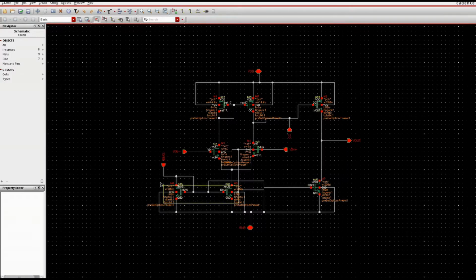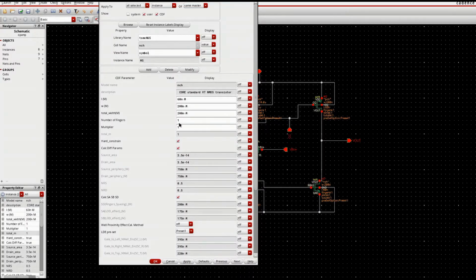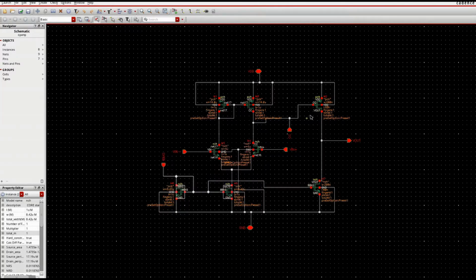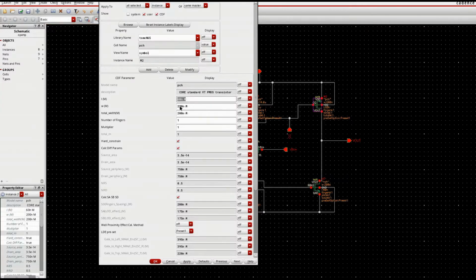Next, these two MOSFETs are equal as per the design. W is 8.42 micro and L is 1 micro. And this is, as per the tuned design, the final value of M6. L is 200 nano and W is 65 micro.